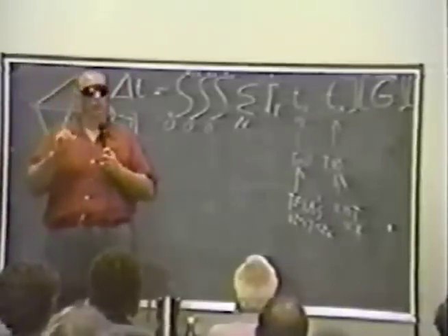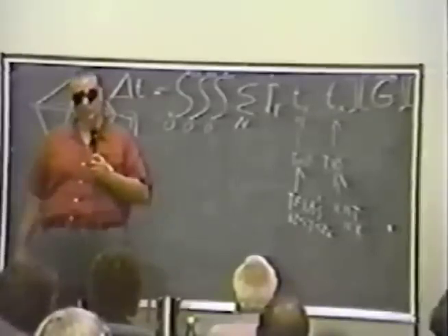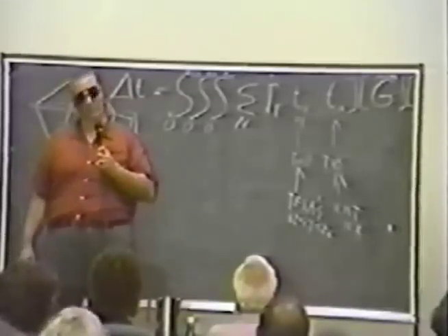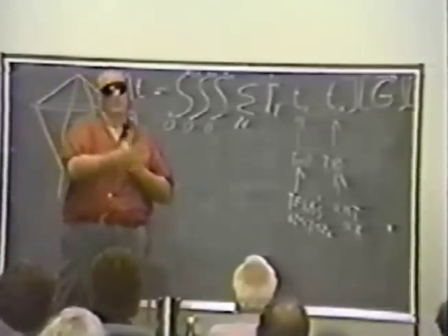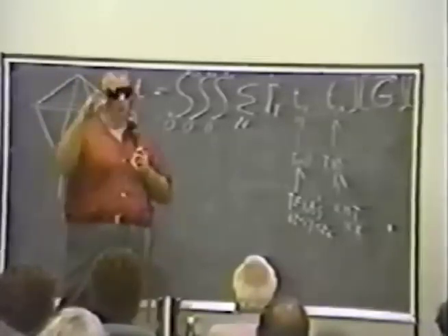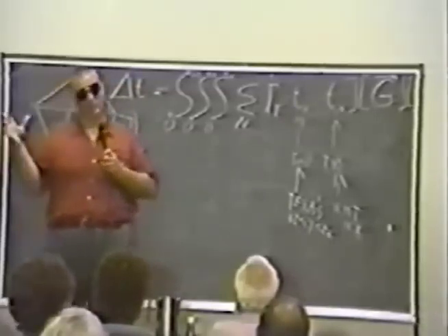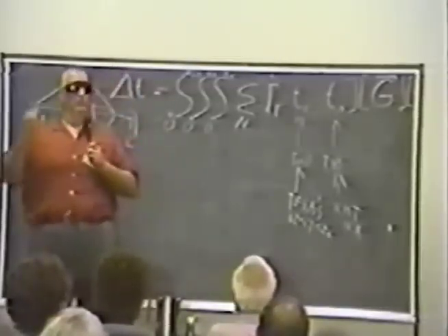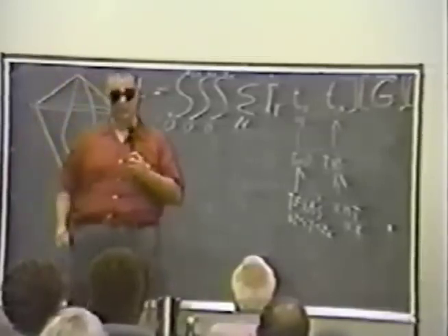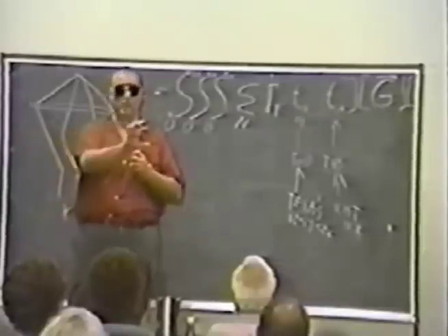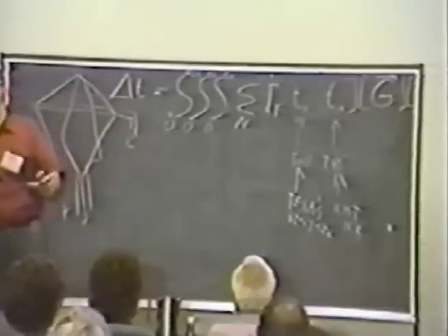Now, I've taken that reference generator and operated that thing from 58 to 62 hertz. Its output frequency did not change once it locked in. When you went below 58 hertz, 57 something, it dropped out of lock, and then the motor tracked the frequency, and when you went above 62 something to 63, same thing happened. So this generator is locking in to something besides the power line frequency, or else you wouldn't have that window where it doesn't change its output frequency. Now, this locks to the rotation of the Earth.